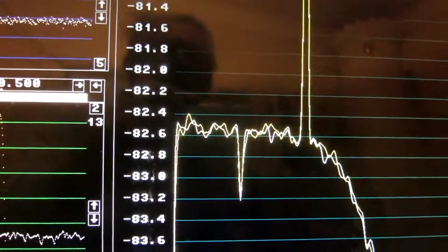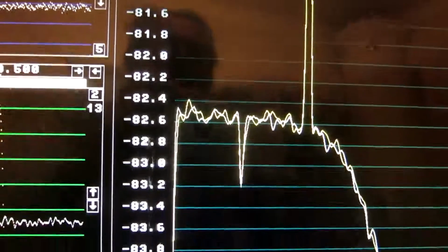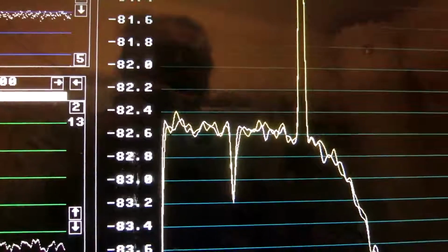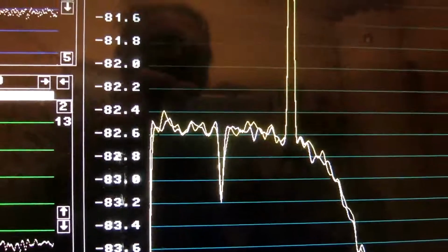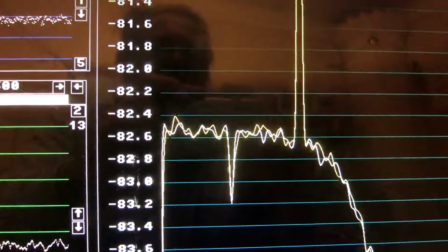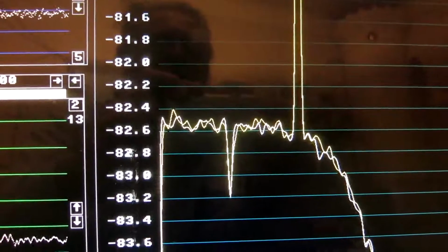So I think I have corrected now the mistakes. 3 decibels, that was a stupid mistake. 0.95 dB, that was setting the bandwidth incorrectly of the transforms. I had set simply 5 Hz and it looked good enough, but it wasn't. It's a little bit below 4 Hz.